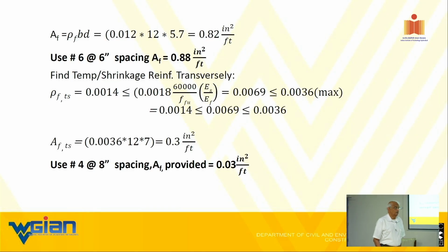You may get the strength, but creep is a killer. If you do not have an adequate amount of aggregate, it can creep like crazy. We never went without coarse aggregate of a certain range. We normally don't go beyond ½ inch for geopolymer concrete.